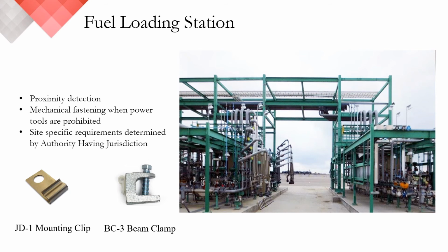the application allows. Again, by treating it with the respect the detector deserves, keeping to a 2.5-inch bend radius, using mounting fasteners that don't stress out the detector, considering the type of detector, the jacketing, the temperature, all of this comes into play, especially when you're dealing with these types of hazards. It comes into play with any hazard.